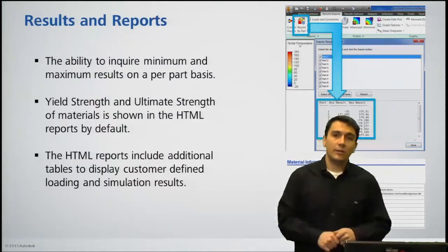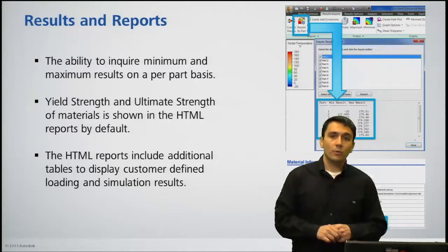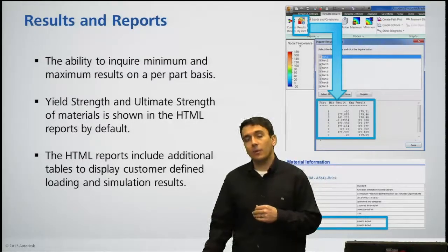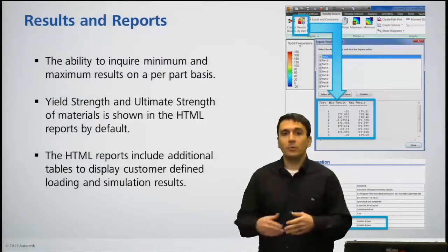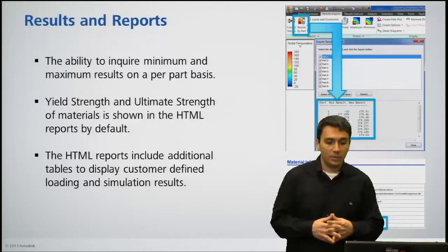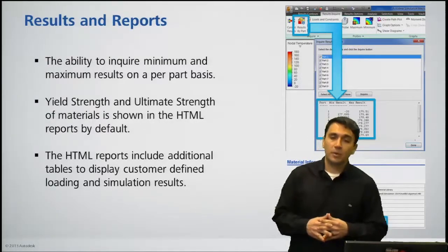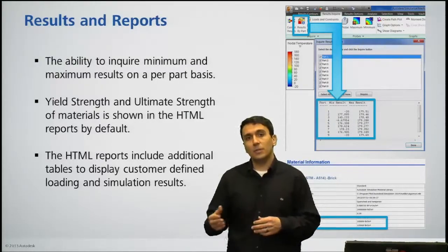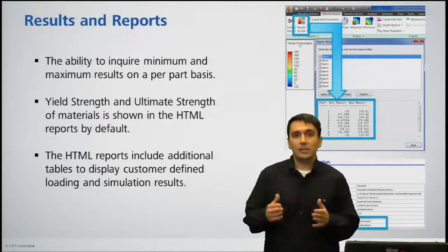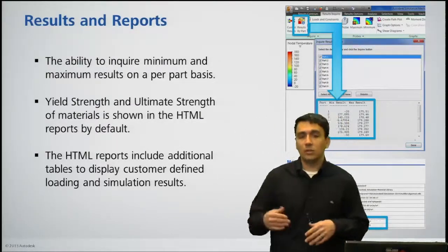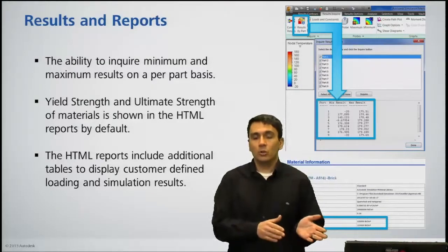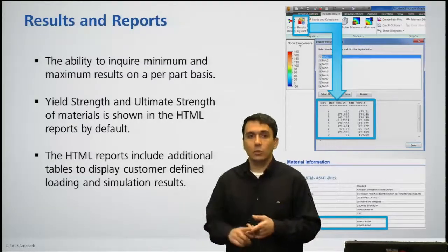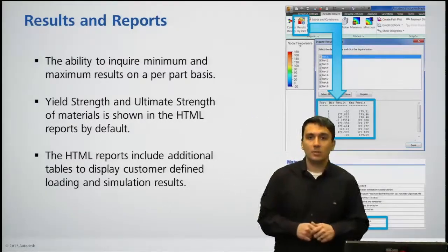And the final one is around our modal analyses. For the modal analyses, we didn't necessarily include a table, but we've added a new file to the bottom of the report where your summary and log files live. Those are the processor information. We've added a new one called mass participation factor. So by simply clicking that file, you will see the mass participation factor for your X, Y, Z directions in both translation and rotation in a clean table that you can, of course, include in your reports and export to your standard Word documents or PDFs or HTML documents.